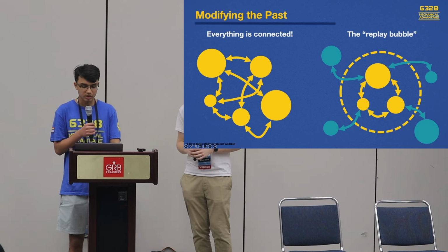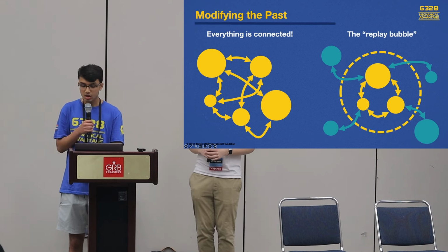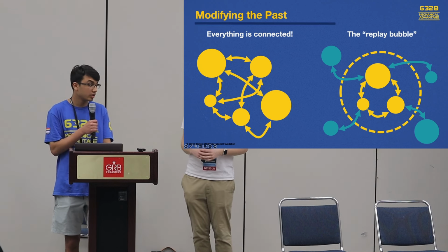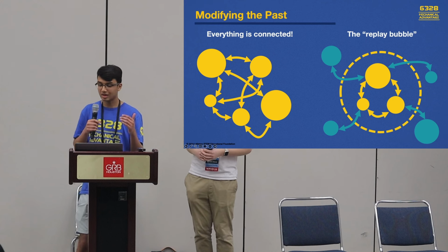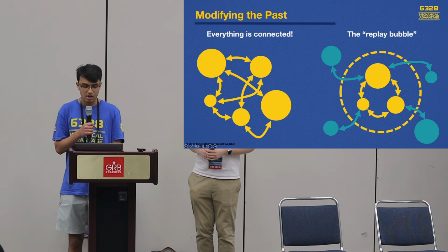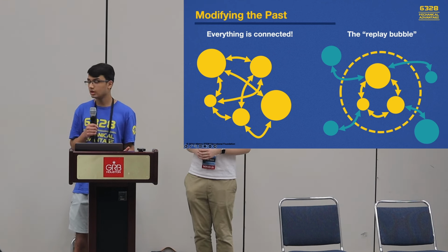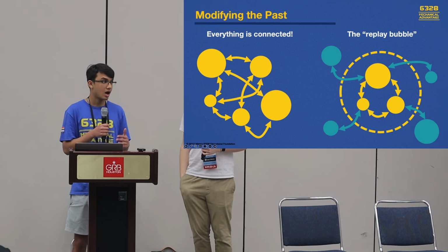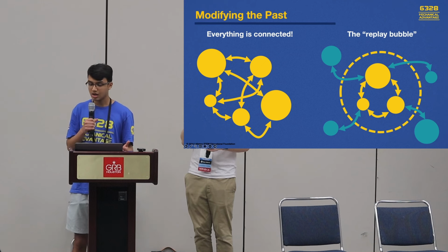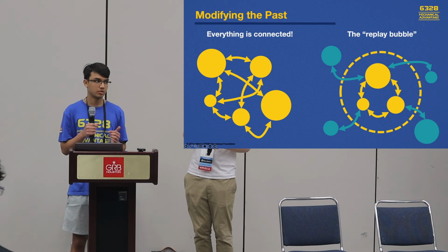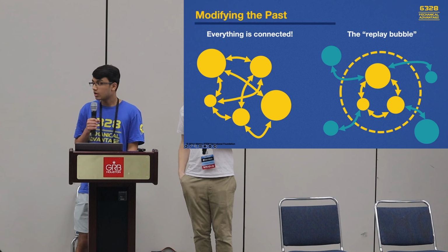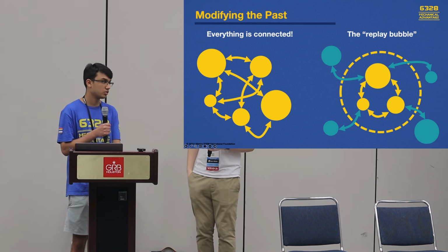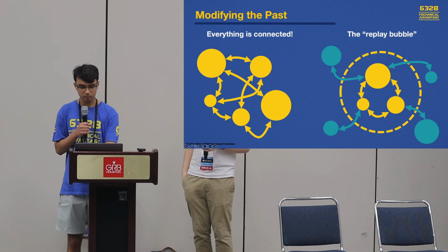Consider the replay bubble. This is a good way to visualize what AdvantageKit is doing. Some parts of the code can be replayed, but other parts cannot. The part that can be replayed can be thought of like a bubble. Anything coming into the bubble needs to be logged by AdvantageKit. Anything outside the bubble is free to read or write without logging, but cannot be replayed. Subsystems are in the bubble, I/O implementations are outside it. I/O interfaces define the boundary for subsystems. When making modifications, make sure it only affects the robot code inside the bubble, so not the I/O implementations.